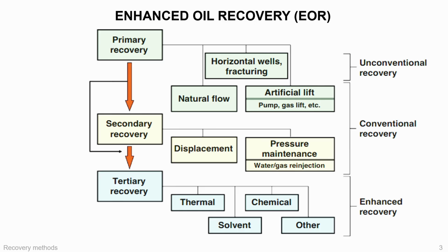Broadly, we can divide EOR into thermal methods, chemical methods, and gas-based methods such as CO2 injection. Each method is suitable for certain reservoir types. Heavy oil reservoirs often benefit from thermal methods. Water-flooded reservoirs with poor sweep efficiency may benefit from chemical EOR. Certain light oil reservoirs may respond well to gas injection, especially if miscibility can be achieved.